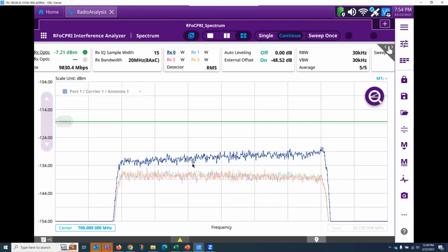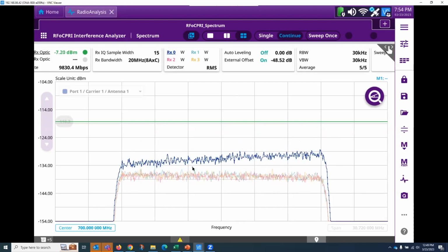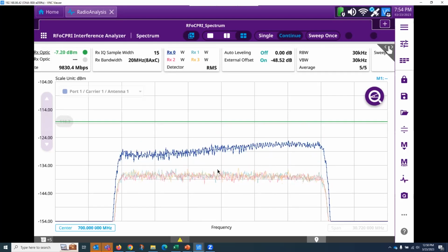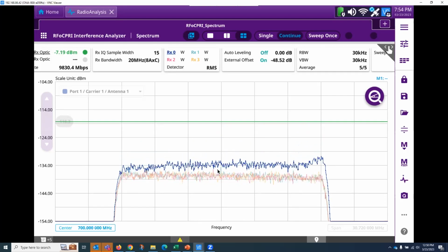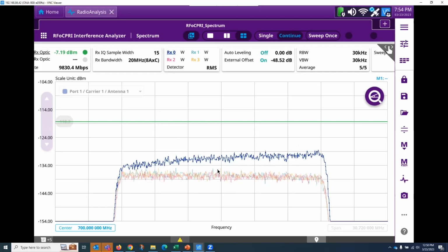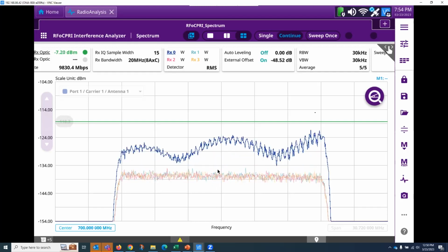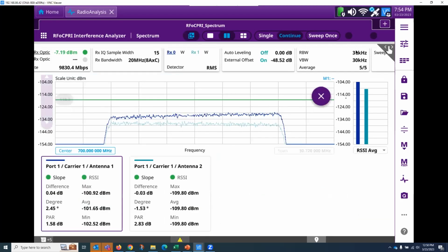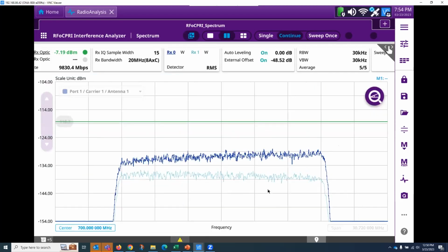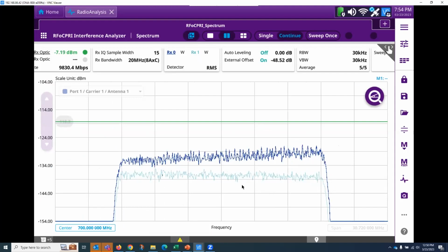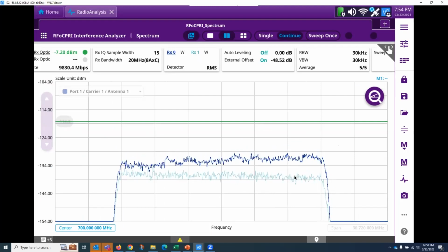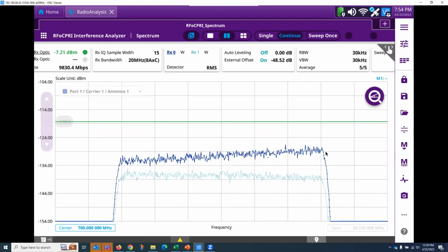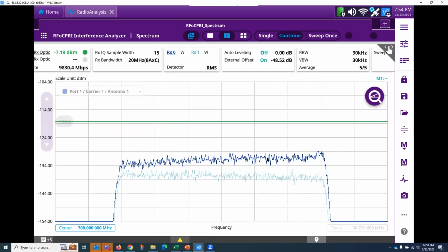In most internal PIM, and there's always a caveat there, it is a single branch, single port, whether it's the coax, the 4.3 adapter, or the antenna itself. That's the problem. I'll show it here with a 2x2 MIMO. Let me separate these and show it as a 2x2. In this case, I've got one that's perfectly flat and is exactly where I'd want to see it, and I've got one that's not. You could allude that this is a single port or an internal problem.